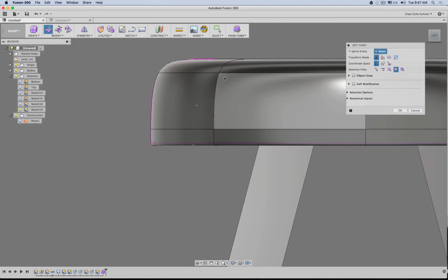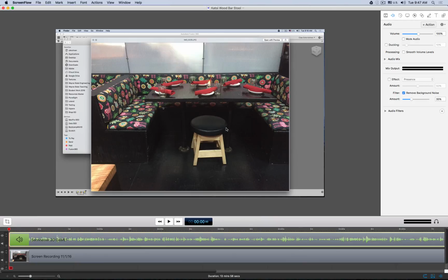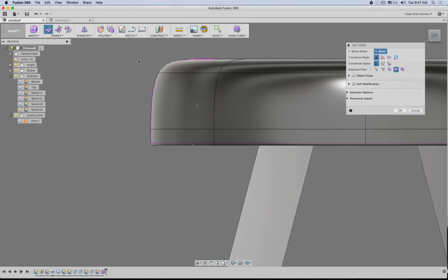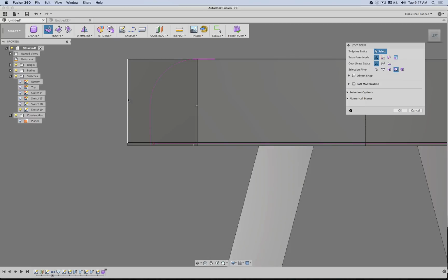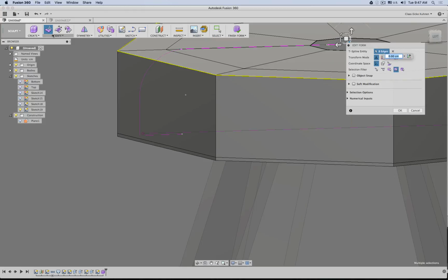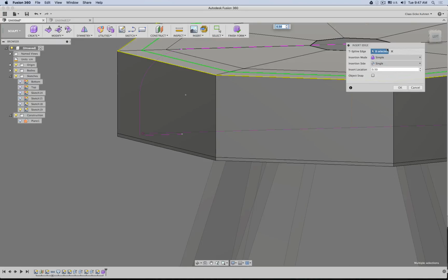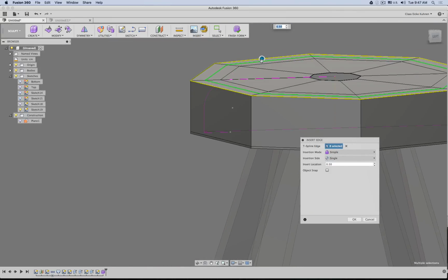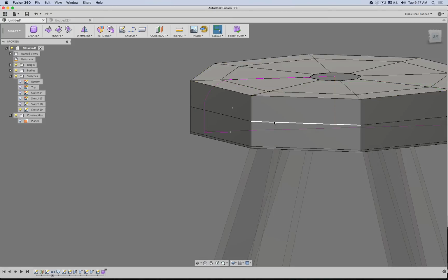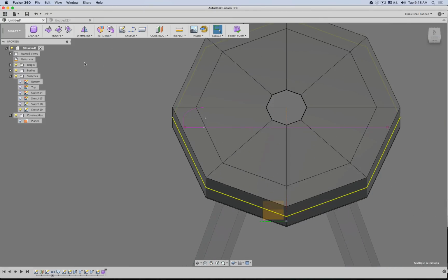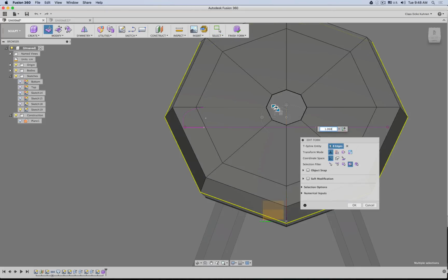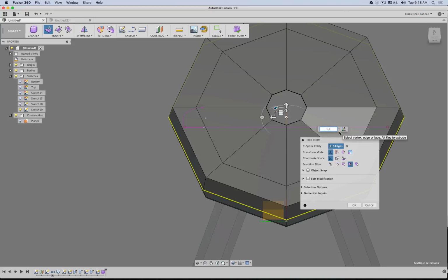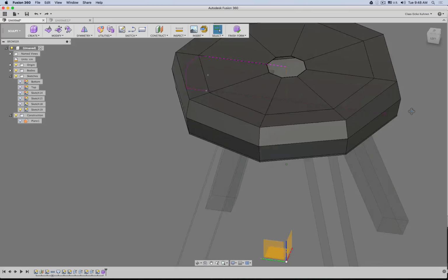And let's take a look. This is fine. This is maybe pillowed out a little bit more, so that actually means here I might need to have a loop cut. So select the loop cut, modify, insert edge. Where is it? There, wrong direction. There, maybe to the center. Okay. And then this one, in top view, we scale a little bit. Just be careful. We can also always enter the value numerically. And then Control 3.